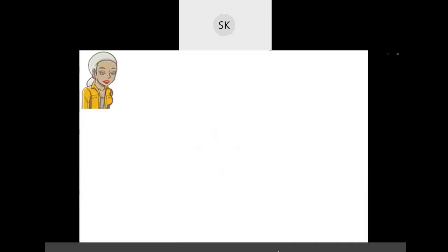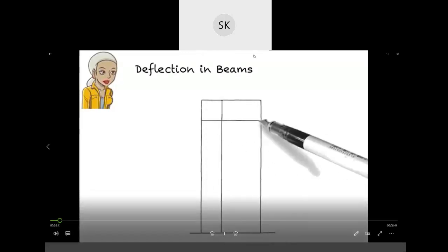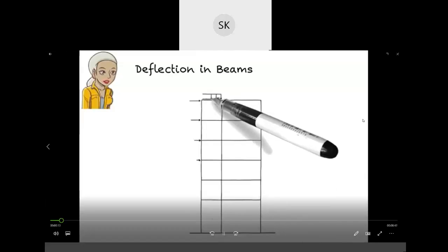Part 1. Suppose we have a cantilever beam of length L subjected to a uniformly distributed load having a magnitude of W. We wish to write a deflection equation for the beam. Assume the beam has a constant modulus of elasticity E and moment of inertia I. To start the double integration method, we must be able to write the bending moment equation for the beam algebraically. See lecture SA07 if you are not sure how to formulate such an equation. To come up with the necessary moment equation, I'm going to cut the beam like this.